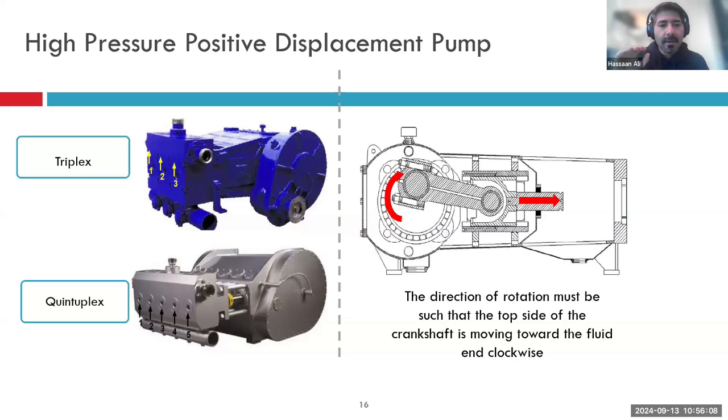There are a lot of sensors that can go on these pumps to ensure that we are catching the signs. One of the telltale signs that you can probably catch early on is high vibration. If your vibration sensors or accelerometers are picking up high vibrations, that means something is about to change, or something is about to fail. So this is what we call prognostic health monitoring, where you are taking temperatures, pressures, and measuring vibrations to figure out when a particular piece of equipment or this pump will fail.